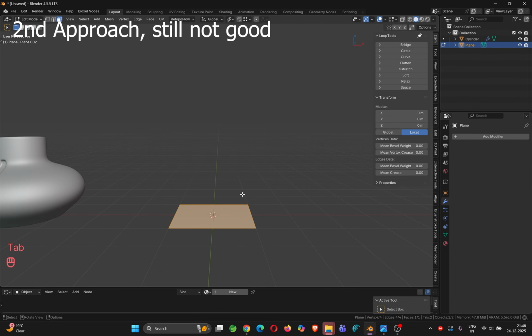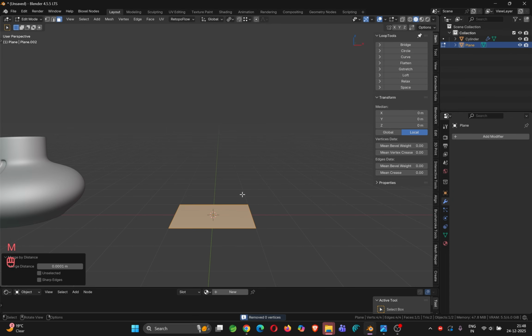You can just go to edit mode and collapse it to a vertex, and then you can basically move this object along the x-axis. Okay, and then change its origin back to the 3D cursor. So however, this vertex has the original 3D cursor. You can now extrude this vertex along Z. Okay, say for example I extruded it up along Z, and then we can add some loop cuts.